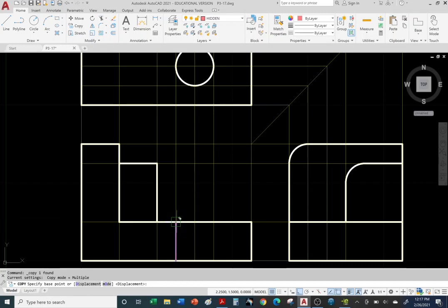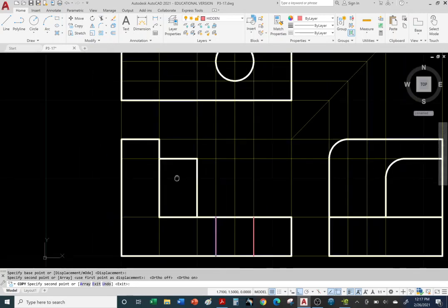There it is. Okay, and let me turn off ortho just so you can see. So obviously it's going to line up with the right quadrant of the hole, or the circular hole, in the top view. And we can click, but let me turn on ortho just to guarantee that it does line up correctly. As you can see, ortho only lets you go vertical or horizontal. And click. And by the way, you can keep on clicking. I'm just going to click for fun, some extra clicks.